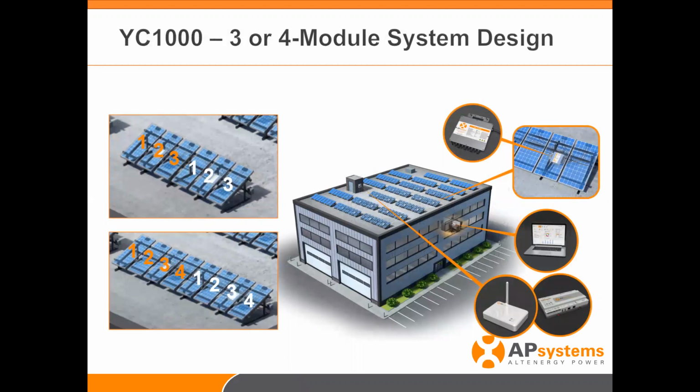This is just an example of different configurations, portrait, landscape, whatever you want, 3 or 4 module designs. Again, because of the flexibility, because it is a single input, you can load it up with different size modules. Customers will say, well, okay, you've only got 1130 watts AC output. What size modules can I use on this particular device? And again, the answer I always give is, you want to right size, and you want to make sure that you stack the deck in your favor.